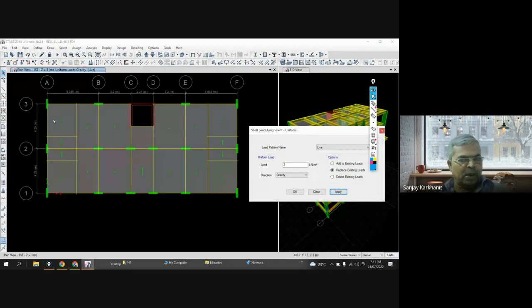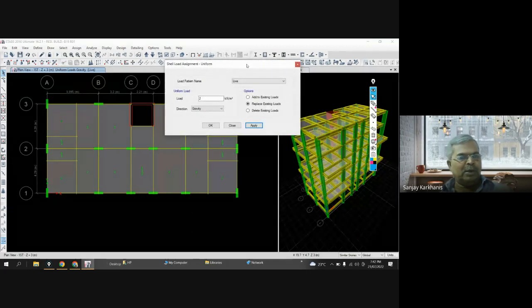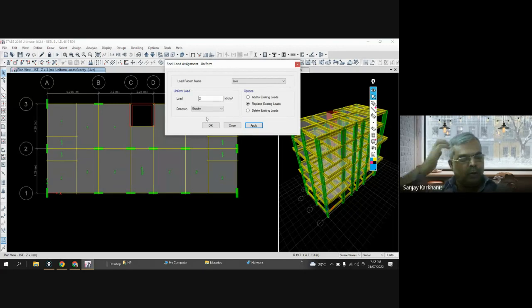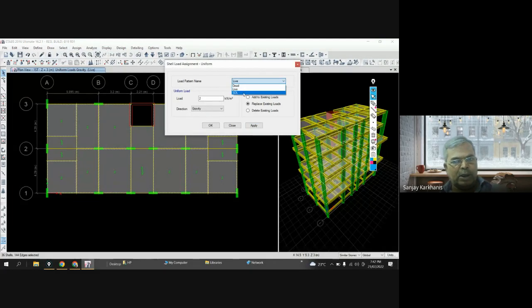Now all these are also a normal slab. That means there will be floor finish. Now it is up to you whatever floor finish you are calculating, let's say it is 1.5. Normally it will be something around 1.25 to 1.5 for a normal slab. So I will again go to Select, click on that, and get previous selection. So all selections that are available, and here you will choose STL, and under that you will say 1.5. Clear?